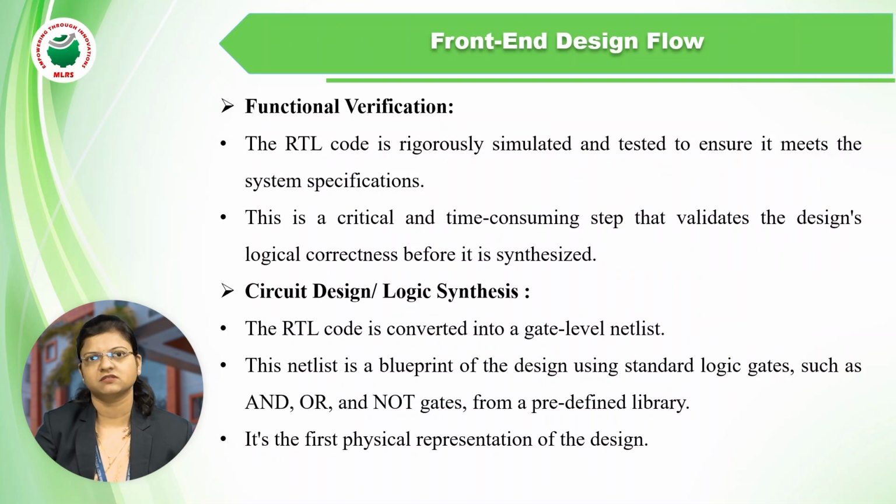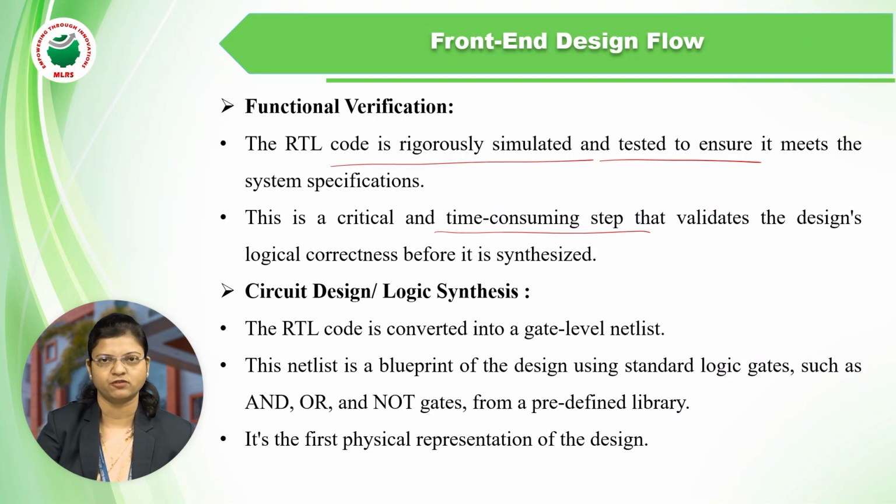Another step is, after writing down the code, we have to verify the functionality. Means we have to check whether the code we have written for any design is correct or not. So we have to simulate that particular RTL code and test it to ensure that it will meet the system specifications or not. It is basically a time consuming process, and it will validate that whatever design logic we have written by using the hardware description language is correct or not before going to the synthesis.